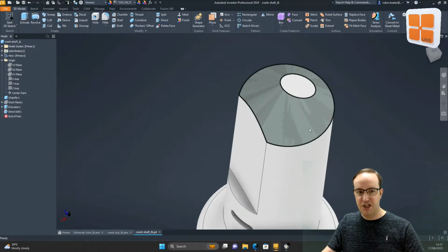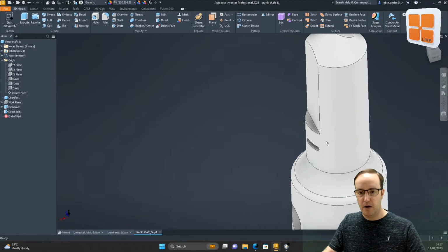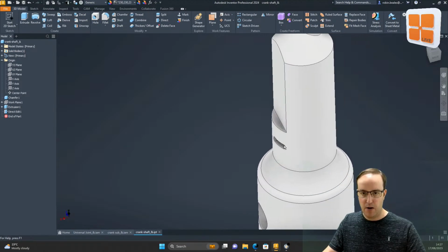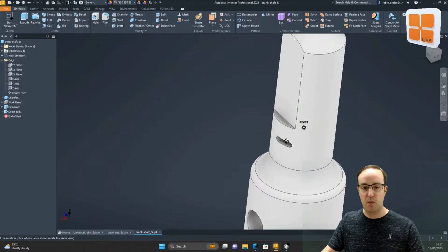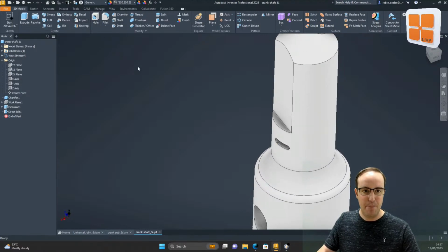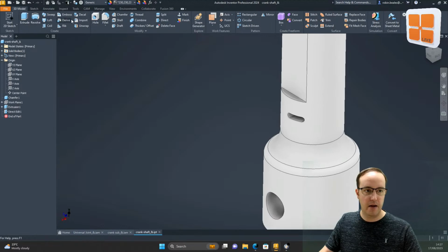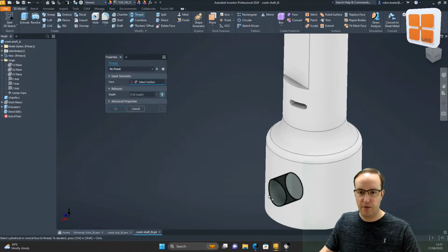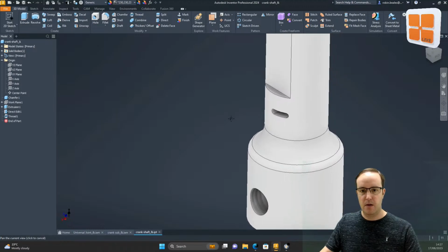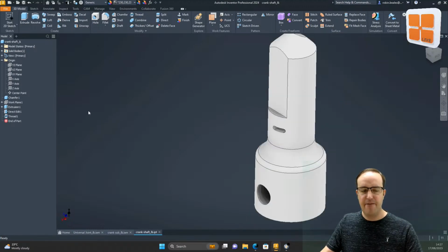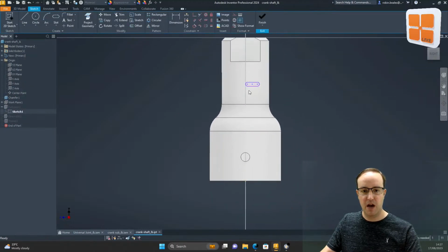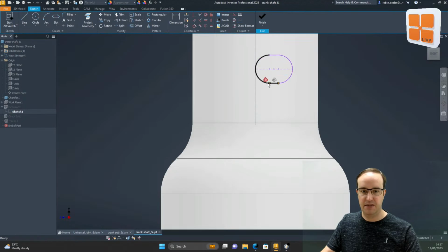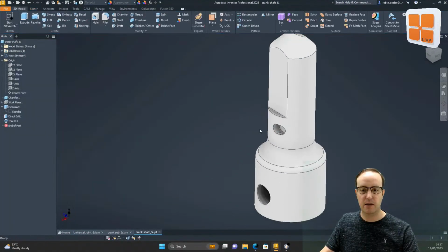As I say, all of these changes that you make, whether they are Autodesk Inventor direct modeling, or original modeling with sketches and features, whether it's a pick and place feature like a thread, let's put a big old thread on that one there, or whether it's one of these direct edits, everything is saved. So here's my import, and then I've got my extrusion that I made back to the original sketch. Just like in SolidWorks, you've got the sketch there. We can go in and we can tweak that. It's the same as you would work inside of SolidWorks.